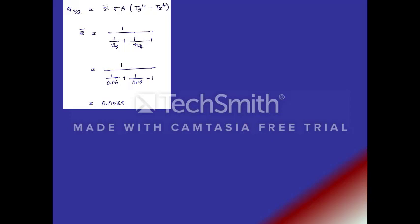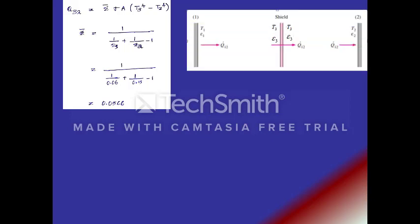So epsilon bar is equal to 1 by epsilon 3 plus 1 by epsilon 2 minus 1. You substitute the values of epsilon 3 and epsilon 2, and you will get 0.0566. So we calculated between surface 3, the shield, and plate 2.